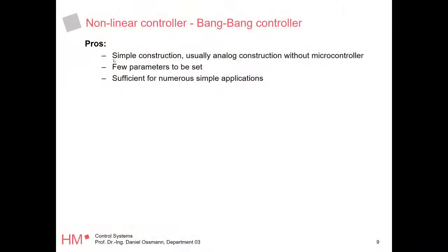To be fair, that's all we have in the lecture for the bang bang controller. There are some pros, some cons, which I'm going to try to summarize. So the pros are really, it's simple, and often you don't need a microcontroller. You can do an analog implementation. You only have a few parameters to set, and it's often sufficient for different applications, like your oven at home, a boiler, right? These are pretty simple. You don't need to have a fancy microcontroller.